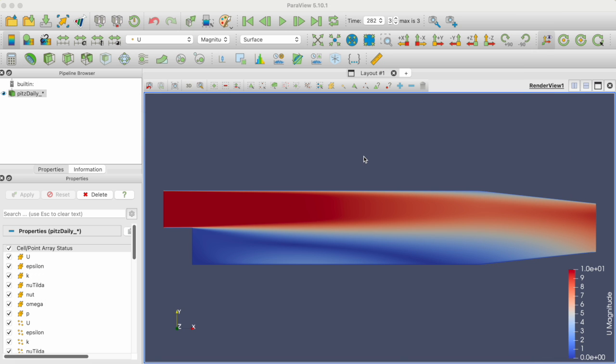So search for a Code_Aster container, for example, if you want Code_Aster. The only thing you have to do is pull the Code_Aster container, run the container, and this will run the code you need. Rather than toiling for hours to find out how to install Code_Aster on your local machine, just install Docker, and in a few lines of code you can have it running for you.